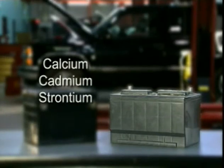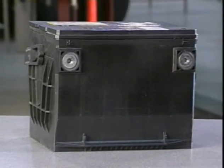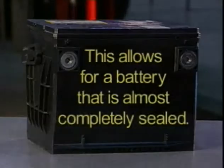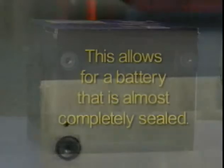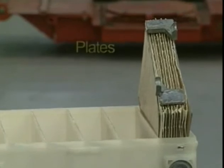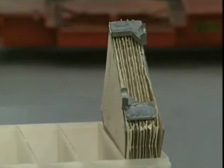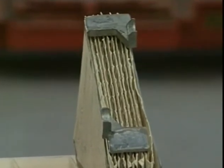On a no-maintenance battery, antimony is eliminated altogether, and since no water is lost, the need for filler caps is eliminated. This allows for a battery that is almost completely sealed. The grids are designed to hold the active materials. They are known as plates. The plates vary in number depending on the amperage rating of the battery. The plates are separated by an insulating material.